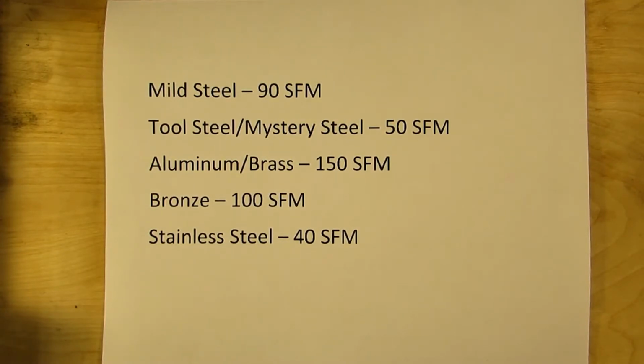So those are actually based on a 15-minute tool life, meaning that at that speed, that corner of that insert should last 15 minutes before you have to flip it to a fresh corner. Obviously, in the home shop world and in non-production shops, that's not really a consideration, whereas tool life might be.